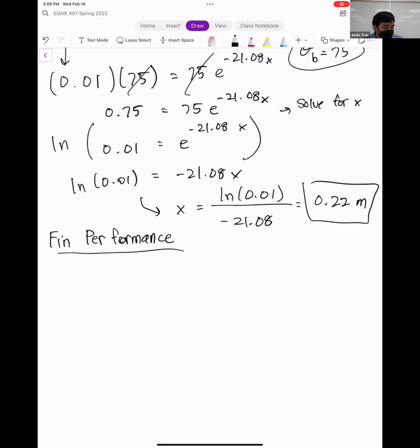Because what you'll see in practice is that when you're doing the thermal design of a device, adding a fin is actually not a trivial thing. It might seem trivial, like you just add a stick on the edge of your device, but that changes a lot of how the device works. It changes the shape factor, so it changes the geometry. It changes whether you can fit your device in a box or something, which is pretty important actually. And then there's also structural considerations, and if it's like a rocket ship or something, it's going to affect the drag properties of your device as well. And so it's not a trivial thing.